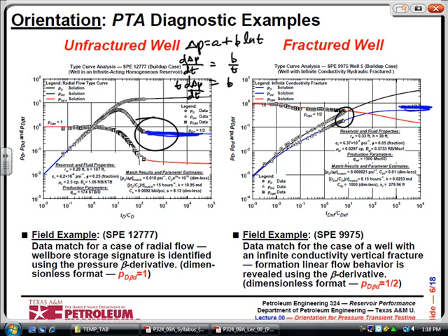But we'll go through all these derivations and discussions and so forth. But if you don't have any data that lies on the blue line, or if your data is not constant, then you cannot estimate the permeability uniquely. That's the point I'm trying to get at. So the first case I'm showing you, we think this is the right answer. But in fact, it could be here, or it could be up here, and this is just an artifact. We don't know. But at least within some degree, we can estimate the permeability.